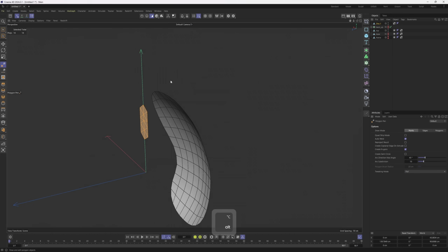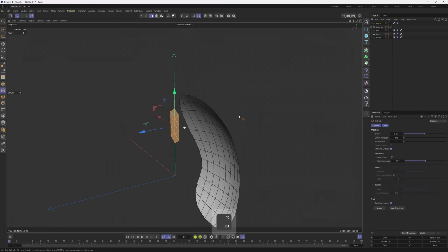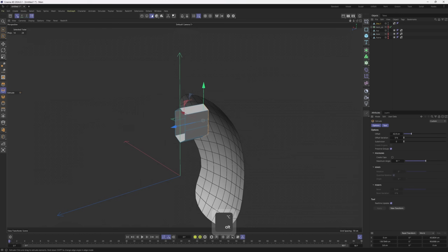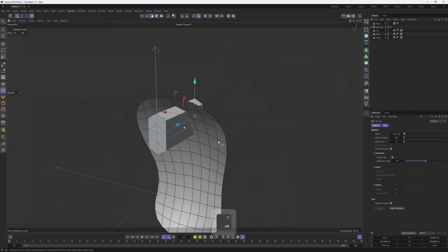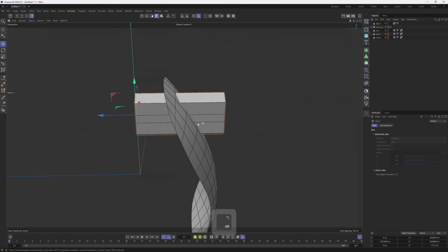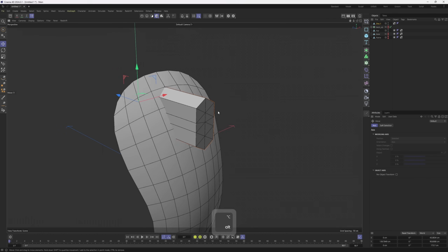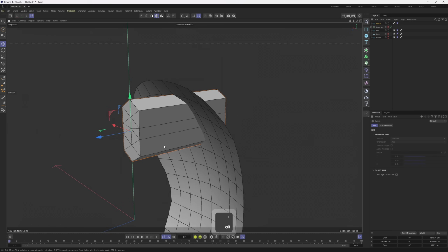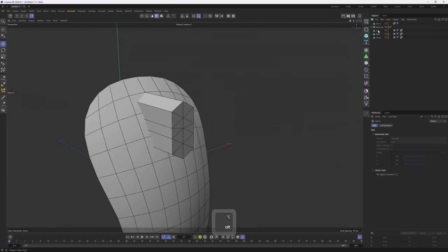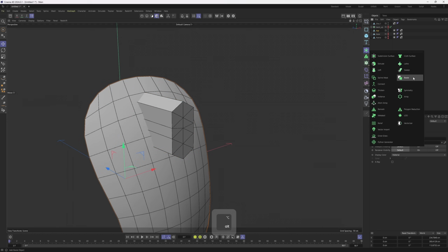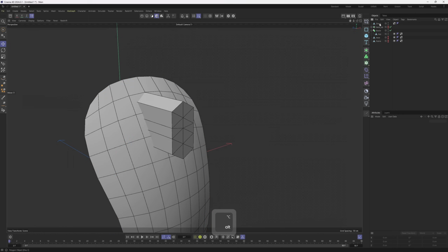Nice. Then I will select all the polygons in polygon mode, select extrude tool, and extrude these across. I will need to enable create caps option because I will use this disk under a bool, so it needs closed caps. Speaking of bool, let's select the top, hold down Alt, and add this one into a bool and put the disk under it.